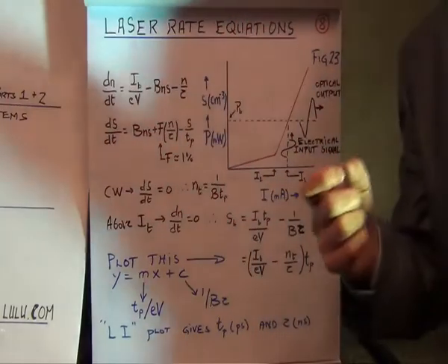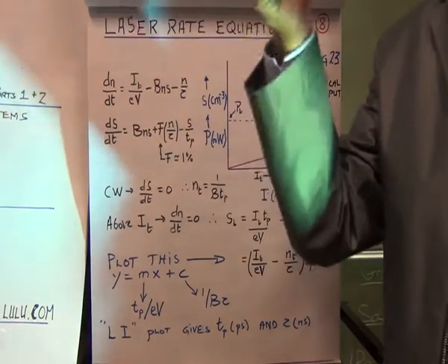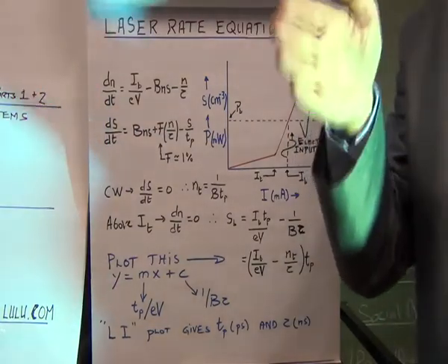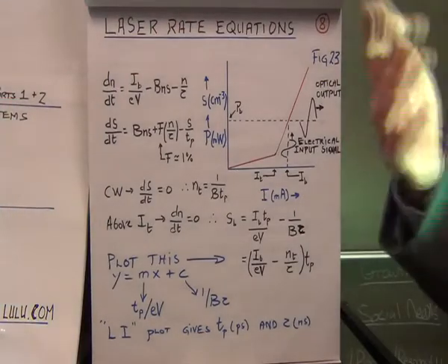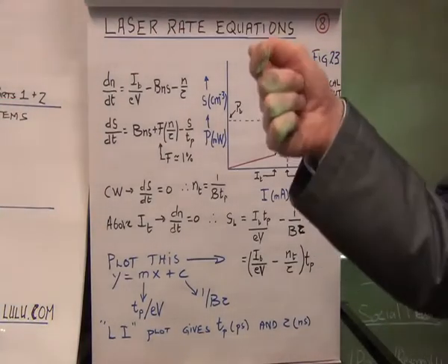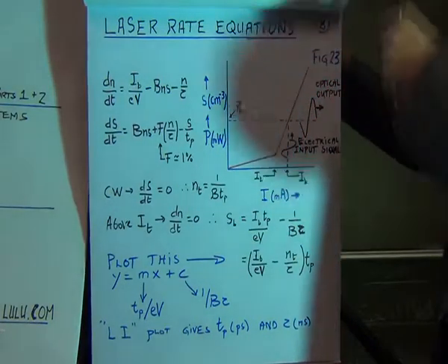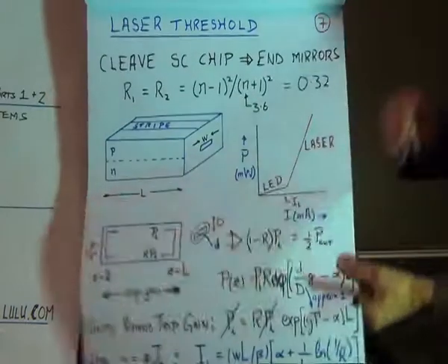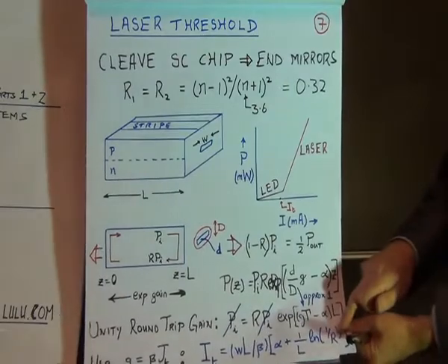That's actually very important. When you connect a laser to an optical fiber, you're putting another window in front of the chip, because the fiber has got a window, a cleaved facet itself, and therefore it'll reflect maybe 5–10% of the light. And if that's reflected back into the chip, go back to your threshold equation, and you'll find there's an R in it. You've effectively changed the reflectivity in the threshold equation.